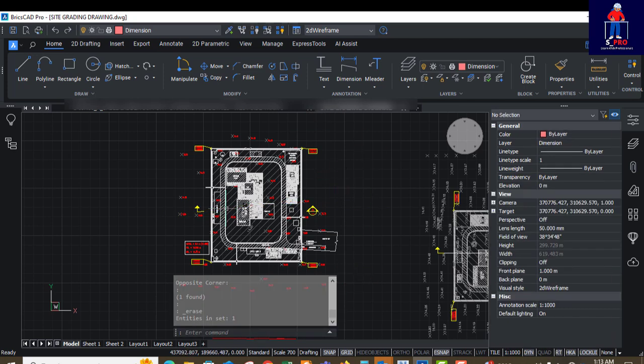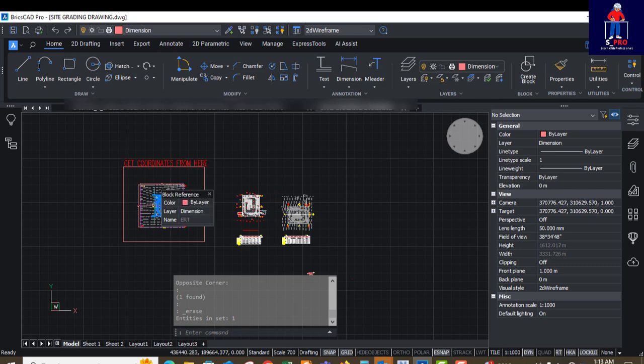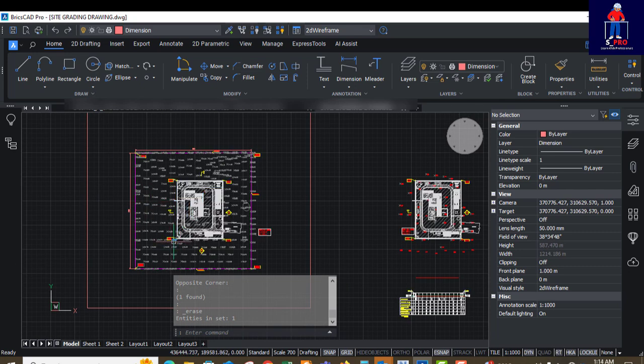And this is all about site grading drawing. Like I told you, the first thing we need to do is to request for a site visit so that you appreciate the terrain of the place, and to be able to also compare the topographical data to what you are witnessing on site. Then you also have to know where you are channeling your water, where the access road is. Then you need to check the spot height very well. If you are raising it up, you determine your design level. You are the designer, you have to determine your design level, but you need to have justification for whatever you are using as design level.